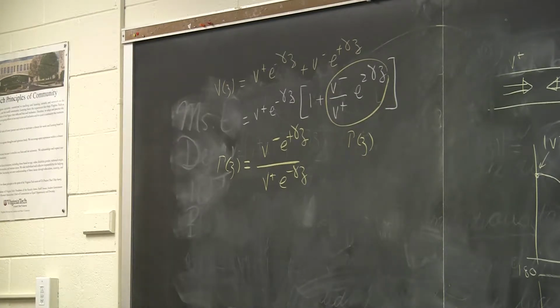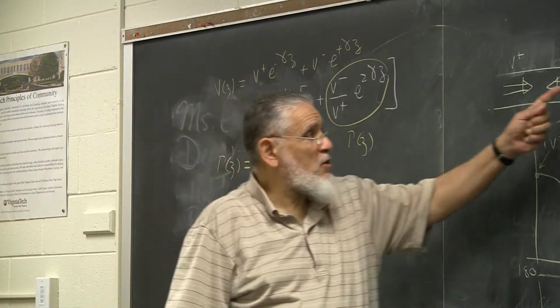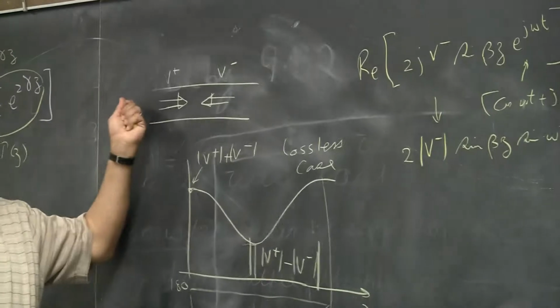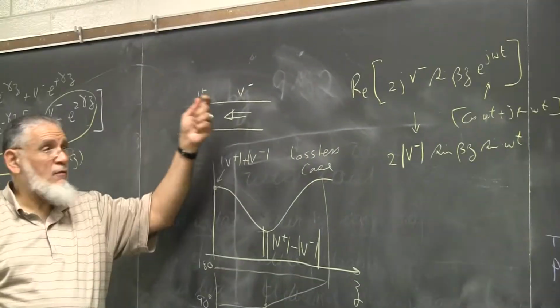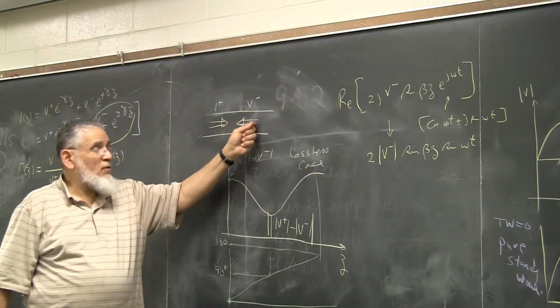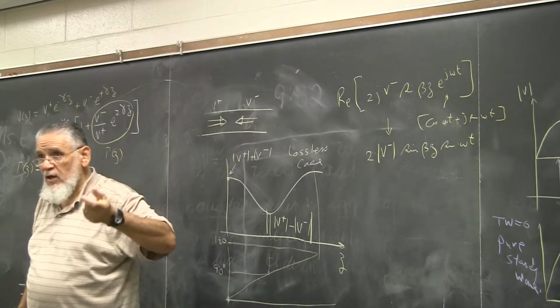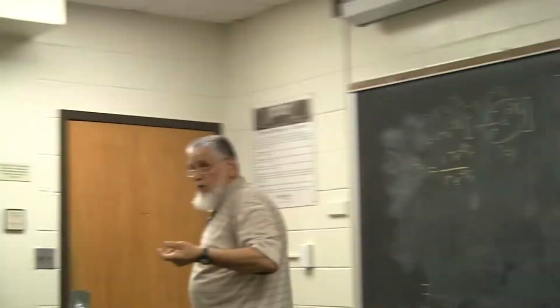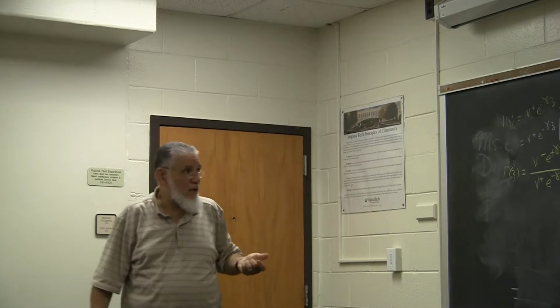This presentation is almost the standard that everyone likes to work with because it brings in a very important and significant physical meaning of the reflection coefficient. Because, like we said here initially, remember we only had one source on the left. We didn't have a source here. So this wave here would come as a result of a reflection from the termination at the far end.